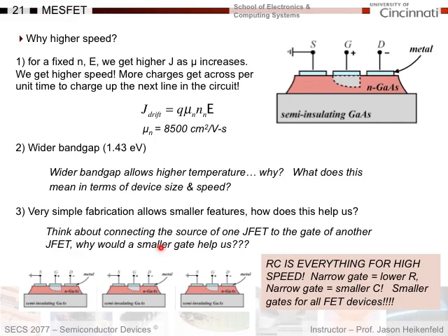First off, the gate we have here has a capacitance, right? This gate basically acts as a capacitor. So I've got a capacitor at my gate, okay? And if I reduce the width of this, I reduce the capacitance because the area of my capacitor went down. That's important because that's half of the RC time constant for a circuit. If I reduce the capacitance with a smaller gate width, I've reduced my capacitance. However, I get another advantage out of this because I also have resistance decreasing as well.